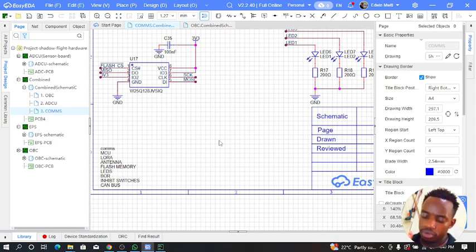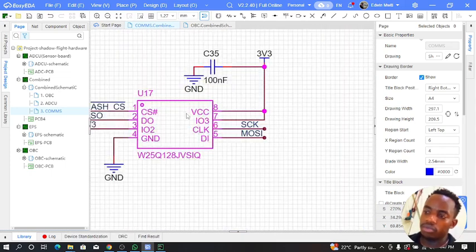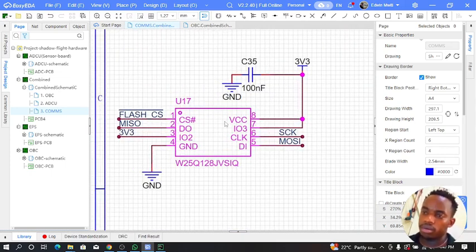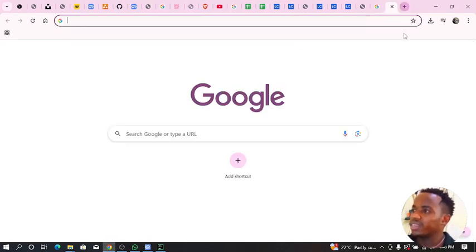If it's supposed to use 3.3 volts, you realize if you go through most MCU data sheets that they give you a time between turning on the power supply and the voltage level stabilizing, right? I think I can show you that from the ESP side.